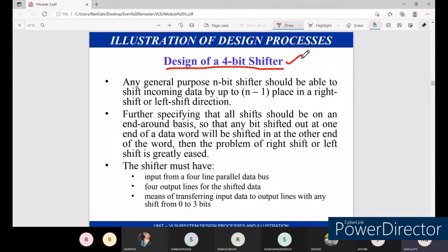Okay, so how can we make use of these shifters in multiplication and division? Can anybody tell me? In the 4-bit shifter, if we shift the given data towards the left side, as I told you, it will act like a multiplier. If I want to multiply the digital data by 2, then I need to shift in the left direction. If I shift the MSB, it will act like a 4-bit left shifter.